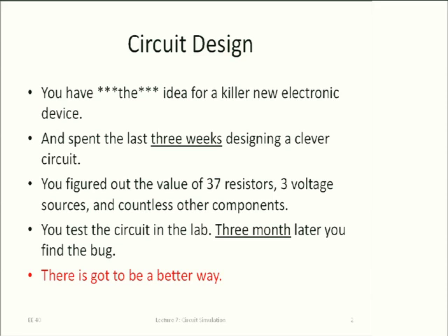In practice, the better way is that instead of just running to the lab and putting together that circuit, we'll actually check it out first with the circuit simulator. Why is that a better way? Well, because with the circuit simulator, it's very easy to say, hey, I want to know the voltage at that node. I want to plot the signal at that thing. In the lab, you have to set up instruments, you have to get to the right place.